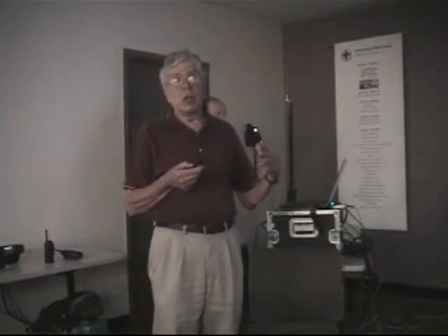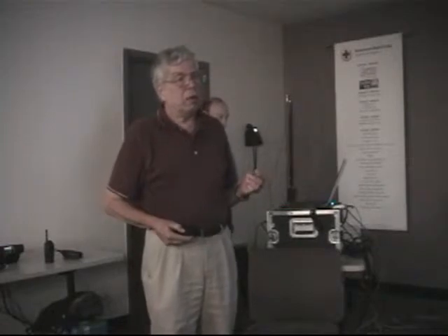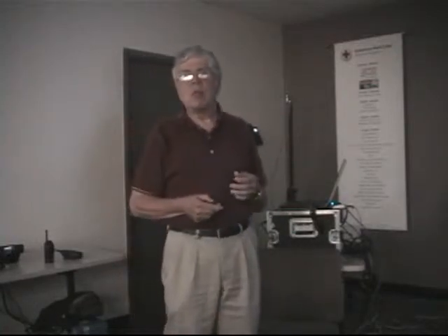And I'll tell you why we put a D-Star repeater on the air in Sarpy County several years ago, and we set out to see how this works. We drove out away from the repeater, and we have a Motorola digital repeater on the same exact tower. The antennas are right next to each other, and we swapped the antennas, and what we found was the D-Star would have problems when we get nowhere near as far as we got with the Motorola.